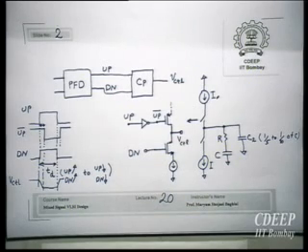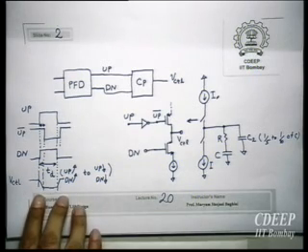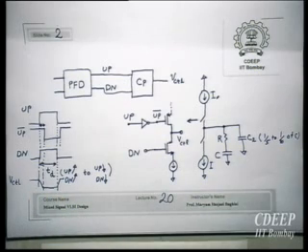This ripple is effectively some sort of distortion. I have some change in control voltage, right? Therefore, the frequency of the VCO will change during this time. Effectively, we want the amplitude of this ripple to be very low, and we want to avoid this variation of frequency. This creates nonlinearity.